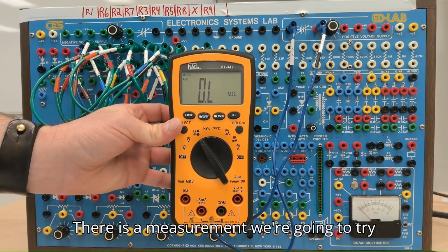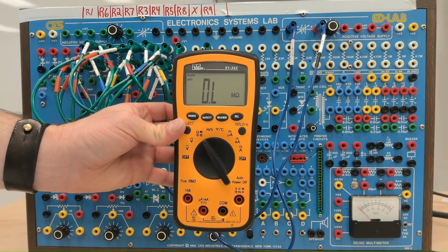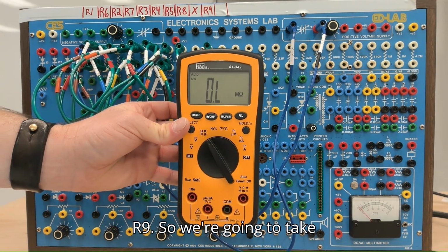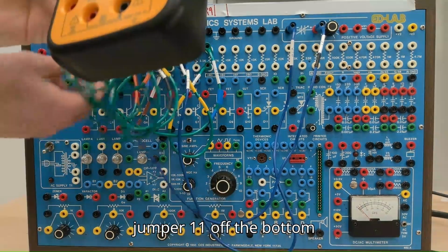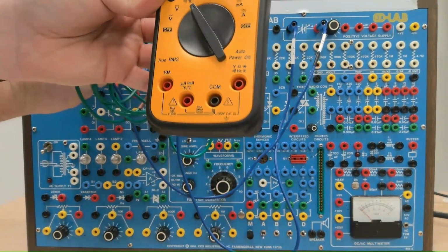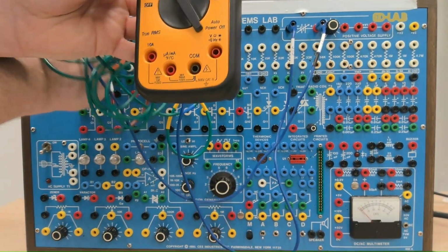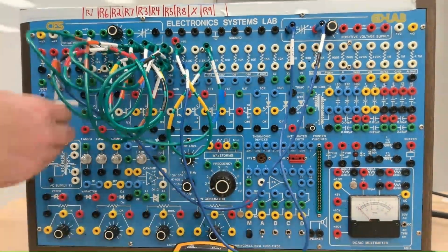The resistance measurement we're going to try to get next is R8, R9. So we're going to take jumper 11 off the bottom side of R6. Jumper 11, the bottom side of R6.